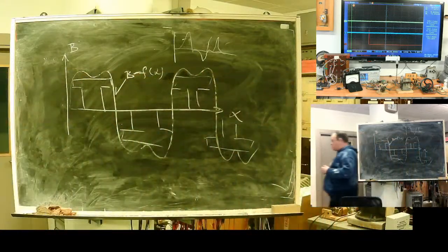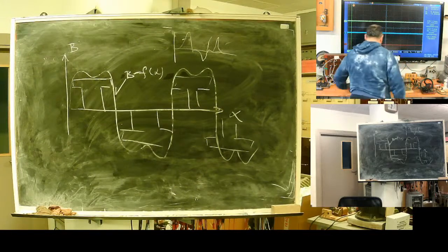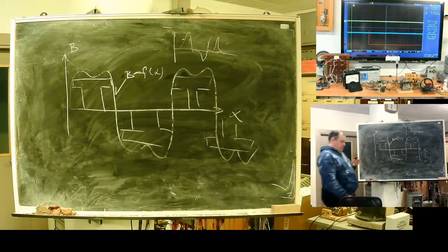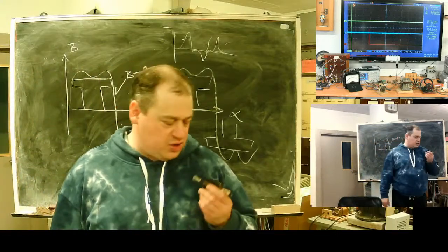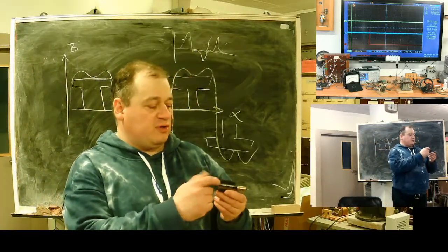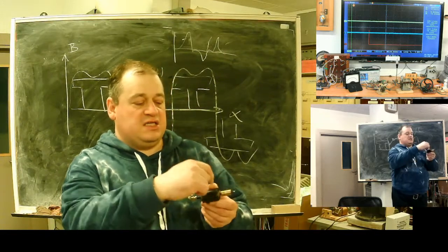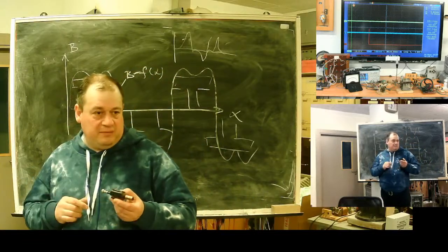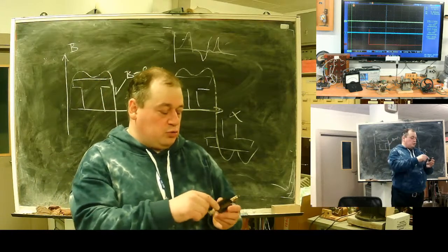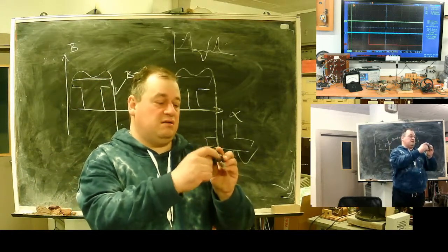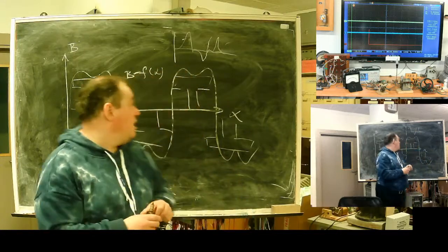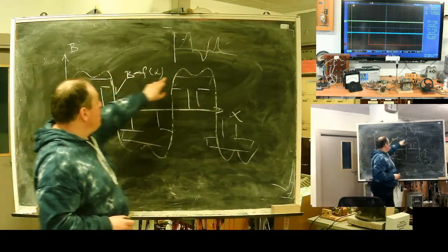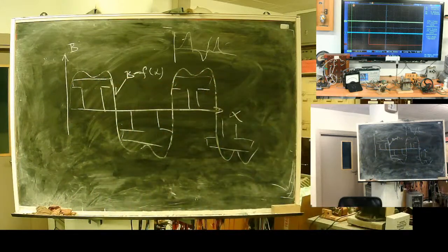Wait, this. Hey. If you disassemble a generator from, let's say, a ship's diesel or something like this, you can find that the rotor has cuts in these areas filled with insulating material, something like micarta or G10. These cuts are made to make the magnetic resistance of the side areas higher, and also lower these parts of the induction curve. But at present we saw single-phase generators, yeah?